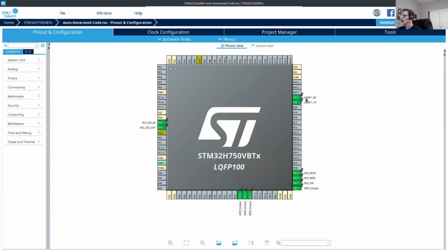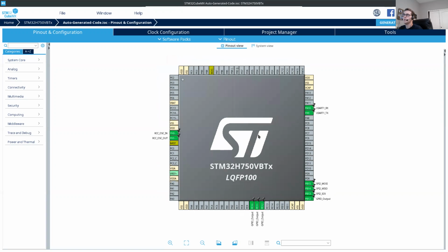This USART here is being used for the USB, and these GPIO outputs are the LED, and this is the external oscillator, which is what we use as the source of our clock signal. But I'll do this tutorial assuming I2C, as that's probably what most of the new drivers are going to be using. But you would do the same-ish procedure for whatever peripheral you're working with.